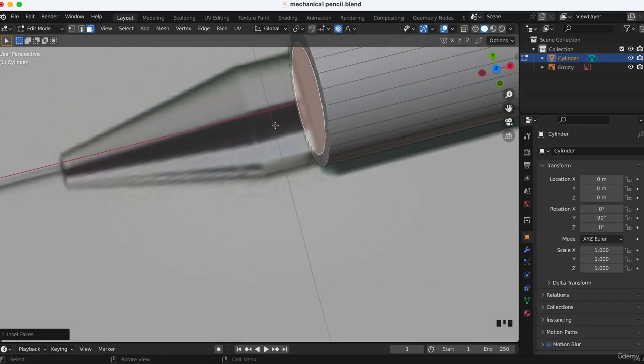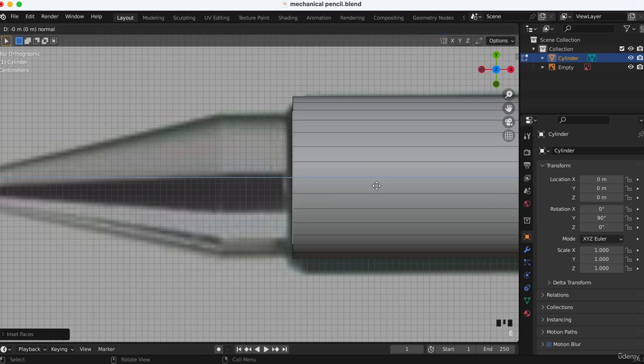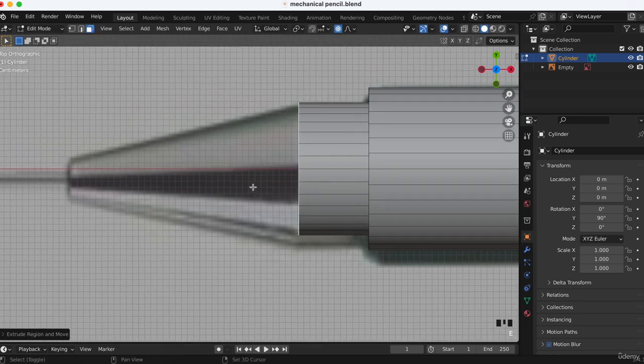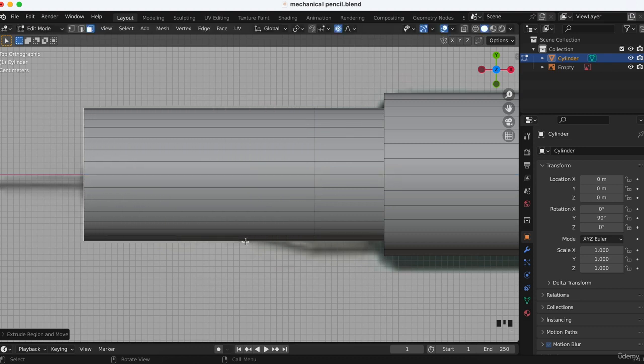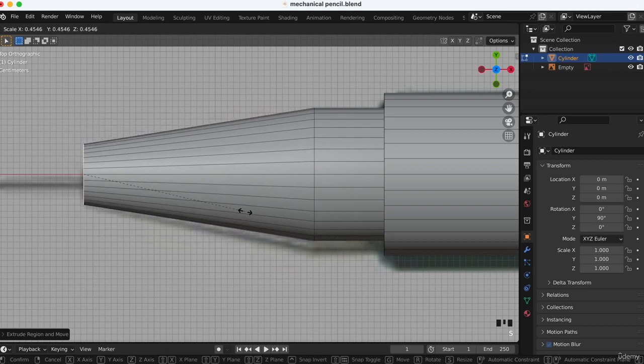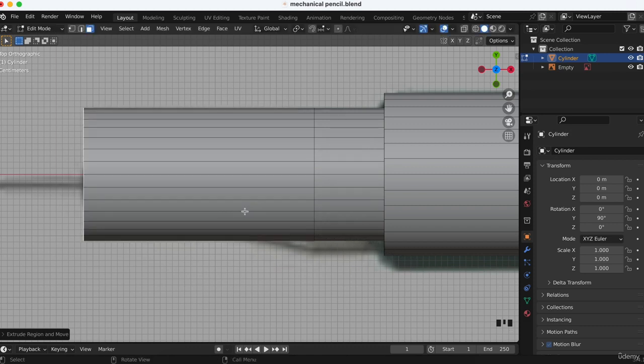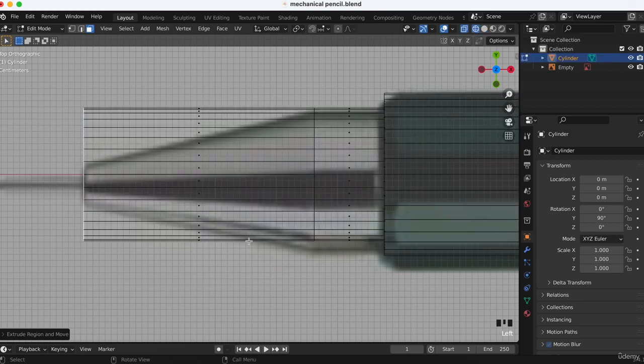And now we can extrude to make this part and then this other part, because here you can see it is right like this, straight, and then it changes direction, so we need to do one and then another one here. So we go numpad 7, E, we extrude here, then we stop, and then E to extrude here, and then S. And we don't want this proportional editing, S. And also I'm gonna exit and put on a wireframe here to see better, S.